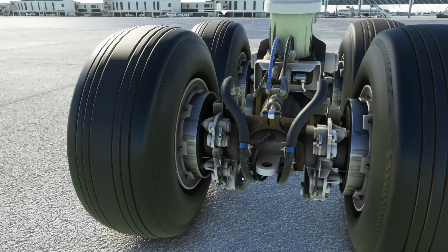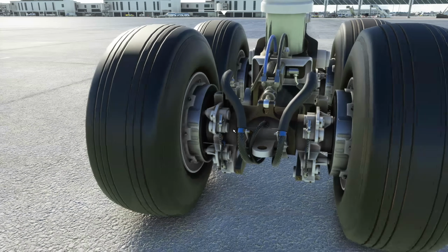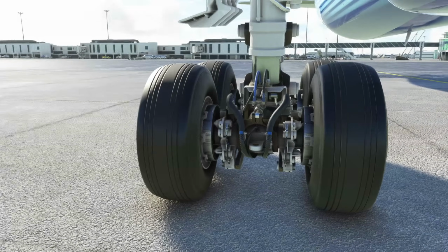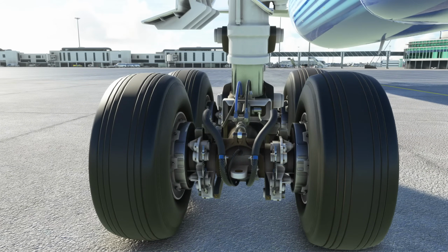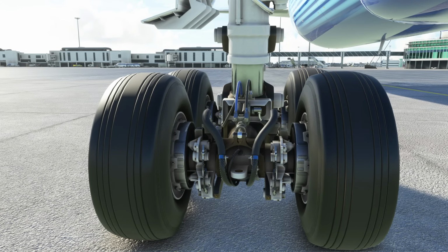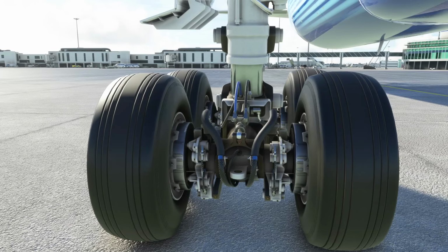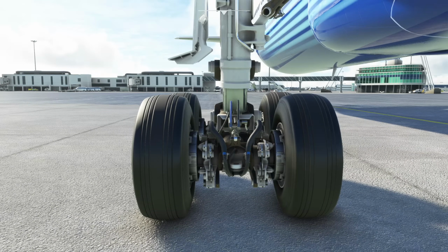These are electronic brakes. These cables are not supplying hydraulic fluid, they're supplying electricity to the braking system. This is a particular advantage to the 787 in the event of any sort of failure, in that you can actually lose all 3 hydraulic systems and still stop the aircraft in a surprisingly short distance, because it can still use the full capability of its wheel brakes. I really like these electric brakes. They're also incredibly responsive and incredibly consistent for us as pilots because of the way they're done electrically. I don't know exactly what the tolerances are of hydraulic systems, but it feels the same aircraft to aircraft. Really like that. But like I say, just from this visual model, they're just missing that additional extra bit.